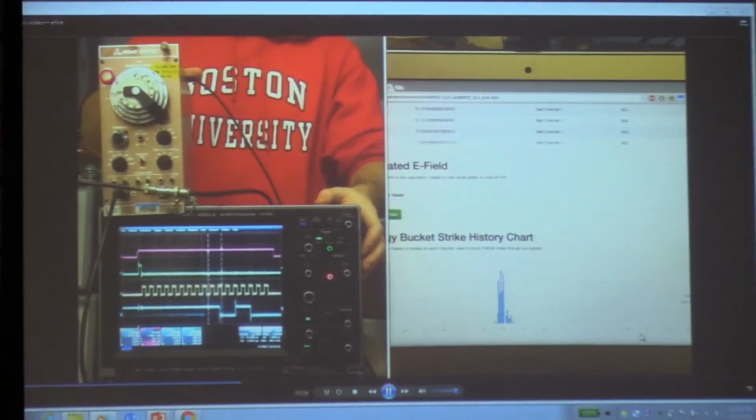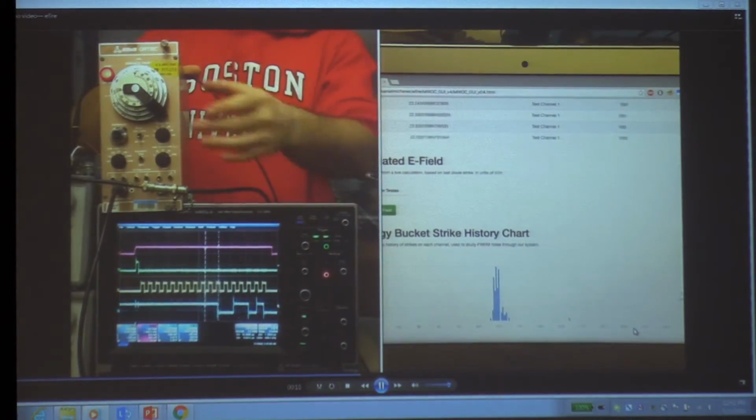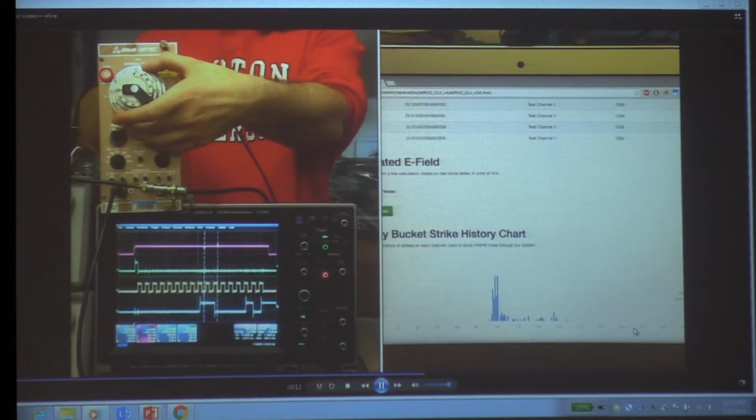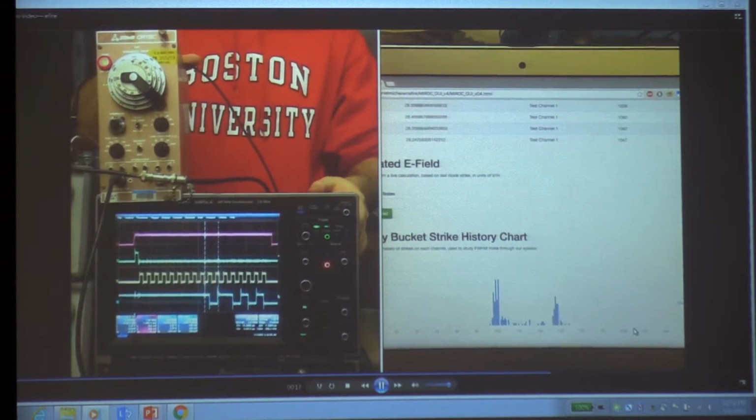So you'll notice the pulser's at one energy setting, and in a minute John's going to change it, and we'll get a distribution of output pulses further to the right along our graph, representing a higher ADC output. And there you go.